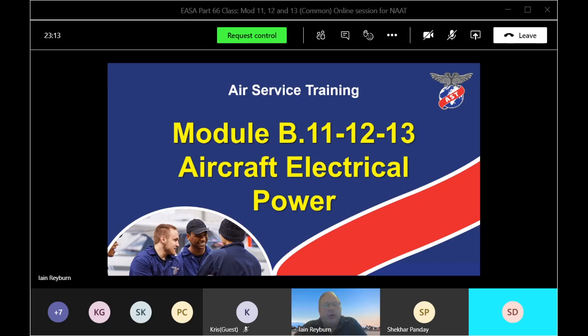The auxiliary contacts. In a basic system, what we would really want is when the main contacts are open, you can see here my auxiliary contacts would be closed, okay? This is just a simple power contactor. So that's the relationship. Our main power contacts are open, my auxiliary contacts will be closed. And if I close my main contacts, my auxiliary contacts are open. And what a contactor does, it allows us to do two things. Remotely switch on my generators, because that could be carrying hundreds of amps.